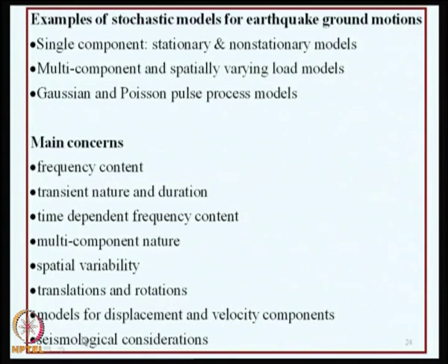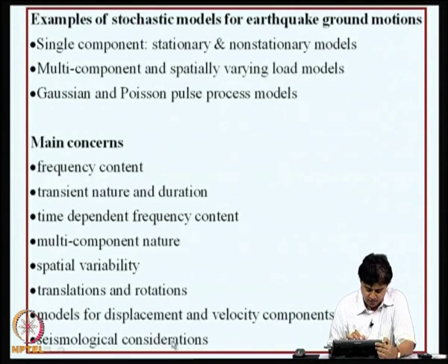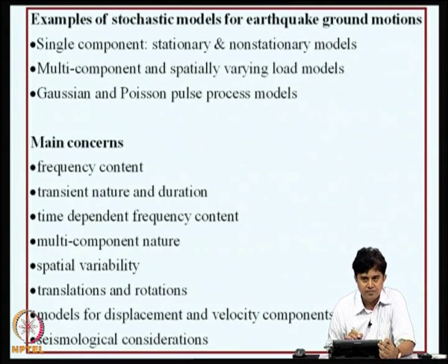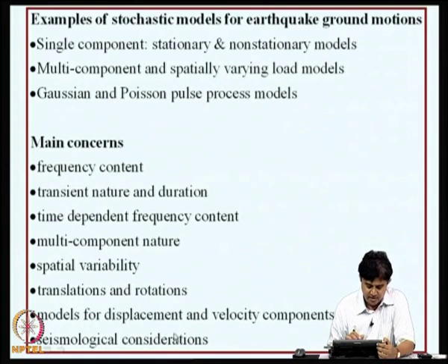Now, we should also think of what are the underlying seismological considerations in arriving at the power spectral density function models. Should we be using a set of instrumental records and then make a model through statistical methods using statistical principles, or should we also include to certain extent the physics of wave propagation from focus to the site. So, some of these issues we will touch upon as we go along.